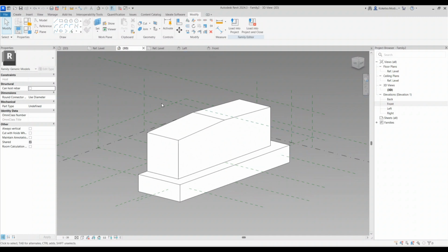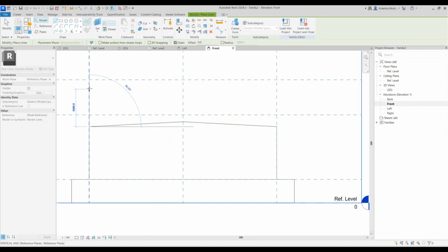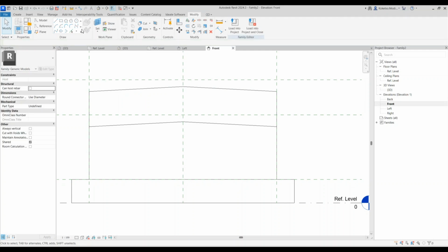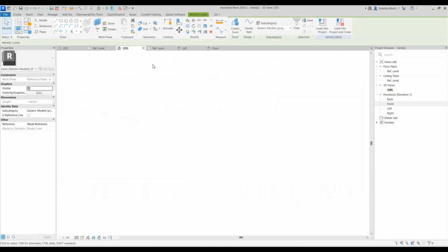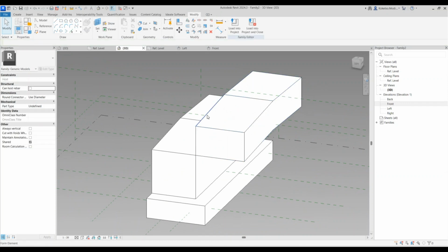All right. So after this, we're gonna model our head wall. So I'm gonna go to the front elevation, select my line, and then from this point, I'm gonna take this to the top by let's say 3,000 millimeters. And then I'm gonna place it diagonally like this at 3 degrees. Select these two lines, mirror pickaxes, mirror it towards the other side, select my line and then place it like that. Okay, select this line, go to the 3D view and then create my form.